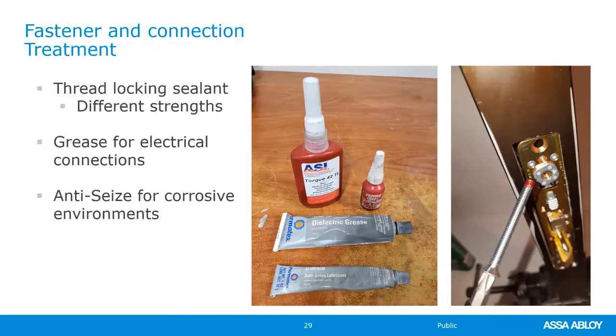Aluminum itself as a material is phenomenal, but it does not hold on to screws very well. It eventually gets loose on its own. You could take a screw that you put into aluminum and made sure it was really tight and just leave that piece of aluminum still and come back a year later and that screw will be loose, because the aluminum eventually gives up the tension that it was using to hold that screw in place. So aluminum storefront door locks get loose frequently just because of the property of aluminum.